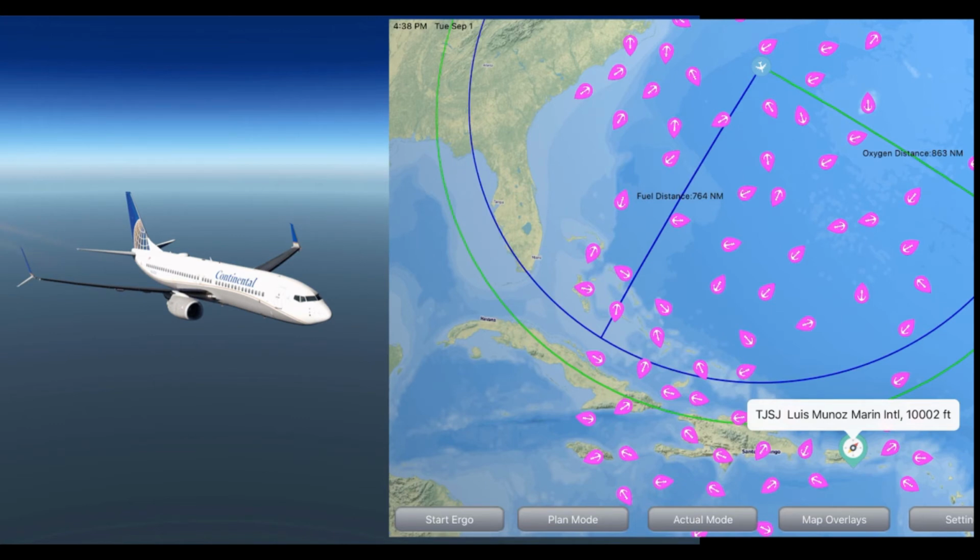After the data is transferred, we'll show you how to use a weather radar for actual ship position verification, and then show you how to construct an autopilot flown instrument approach to a water landing using the aircraft LNAV, VNAV functions.